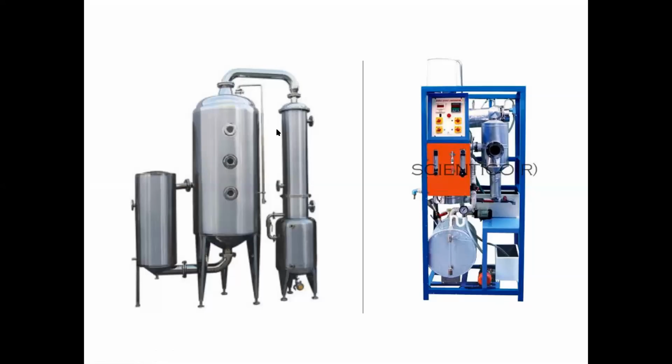Okay. So the point here, we are talking about a major difference between the humidification-dehumidification system and the single effect, the multi-effect, or even the flash, is that here we do not have a carrier gas. A carrier gas has a capacity for the amount of water vapor that it carries, which is determined by the saturation condition. Up to a certain condition, when the air is saturated, or the relative humidity is 100%, it cannot take any further quantities of water.